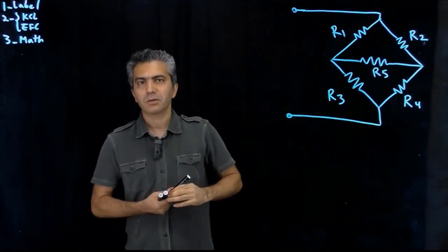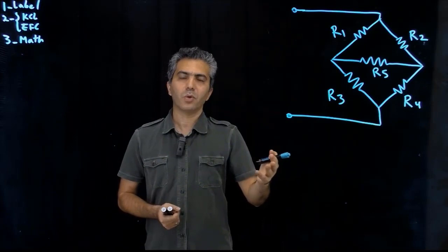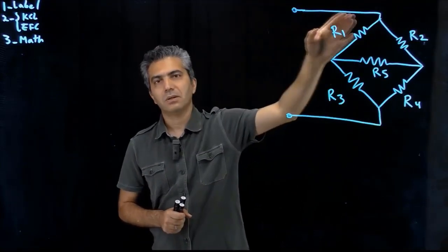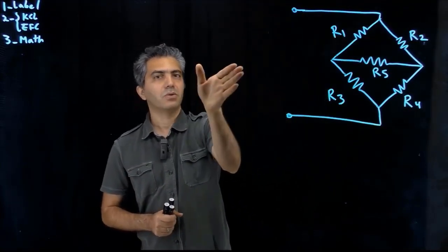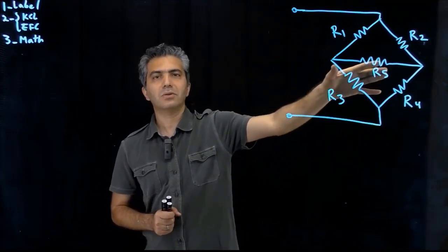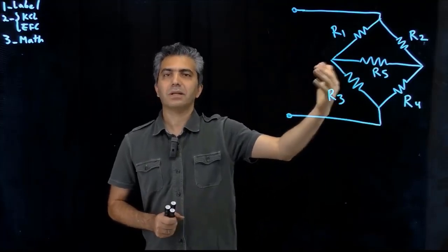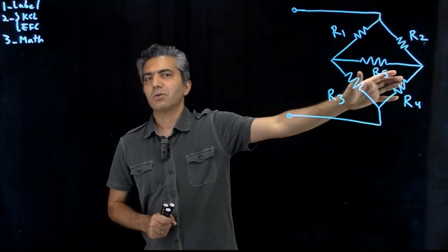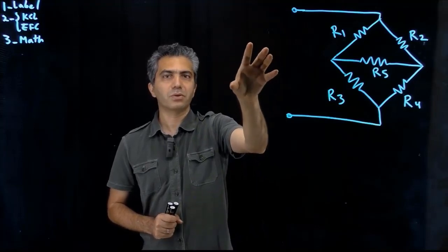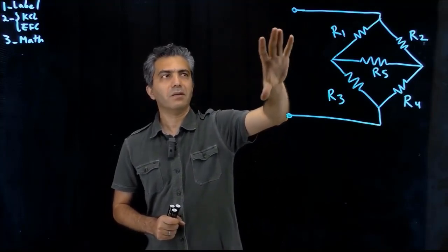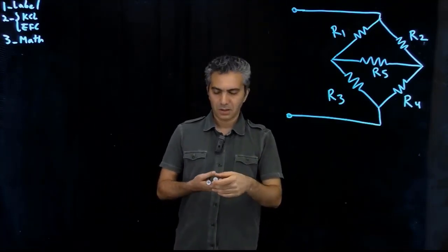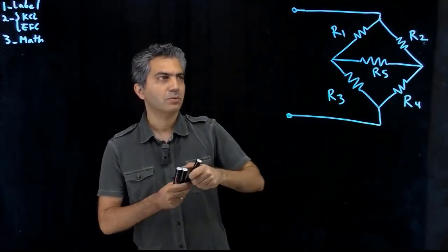So to quickly review, whenever you're asked to calculate an equivalent resistance, what that really means is that you put a box around the circuit and you only see two terminals, and what you're trying to accomplish is to look into those two terminals and assume that internal to that box there's only one resistance and calculate the value for that resistance. Assuming that there's no other sources connected to that circuit, then you can put your own source, voltage source here, or current source for that matter, and divide the voltage that is applied across the two terminals by the current that is going into that, and by definition that's the equivalent resistance. So that's what we're going to do here.